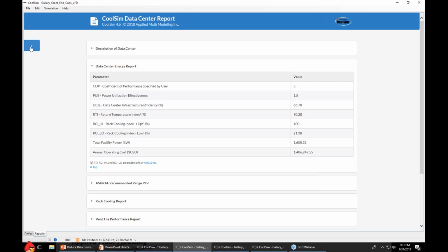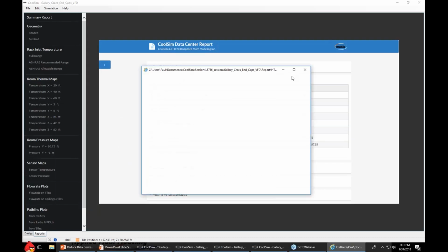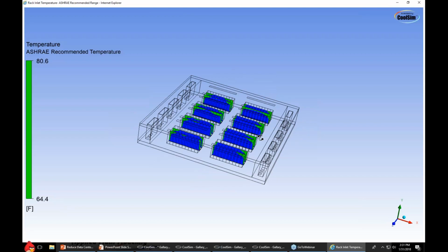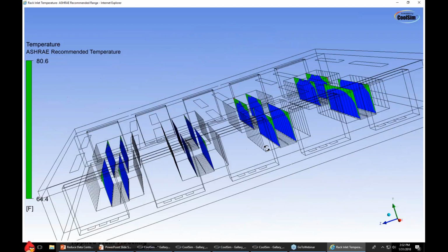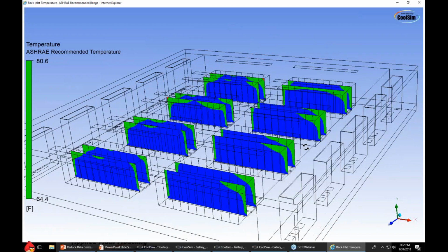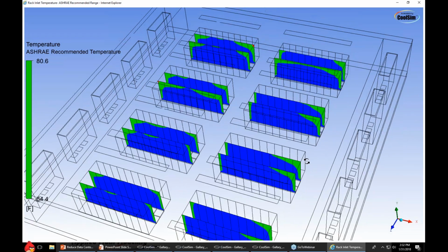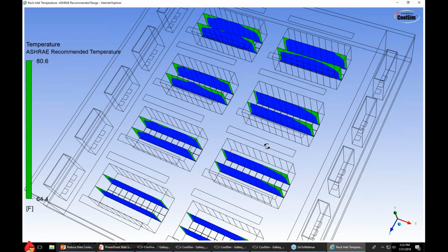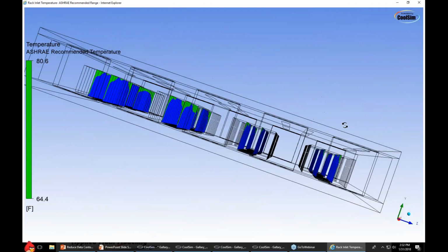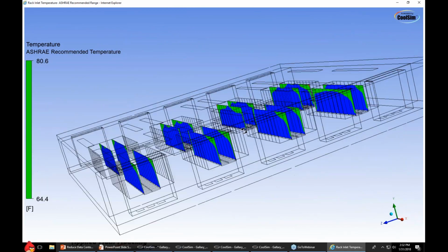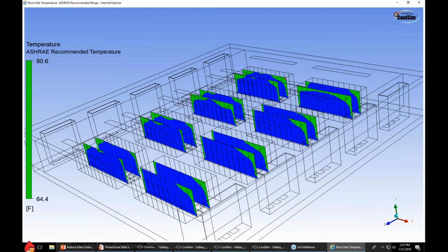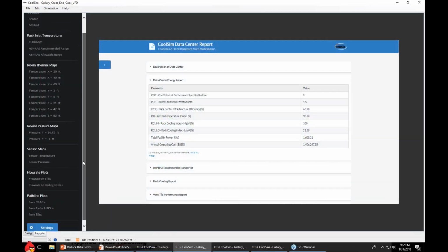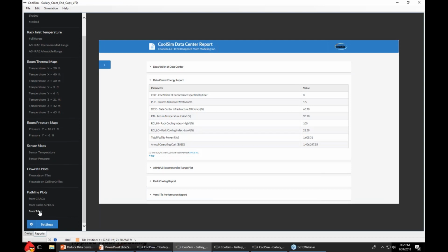So let's go take a look at our racks again at this point and see what we've got. You see we've got some, again, and this is a design that only has end caps on it. The reason I did this is because you can be quite effective with this design. I am not always an advocate of full containment. We could have put a full contained box around that, but there are issues with full containment, such as pressure that you get into with these that this system eliminates. There is no pressure issue here because it's open. And furthermore, it's inexpensive.